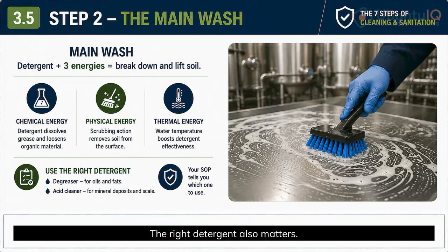Hot water generally makes detergents more effective, but always check the product instructions, because some chemicals actually work best in cold water. The right detergent also matters. A degreaser handles oils and fats. An acid cleaner tackles mineral deposits and scale. Your SOP will tell you which one to use.